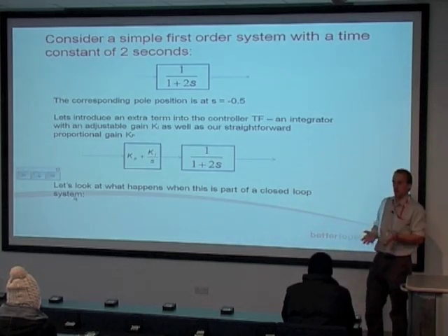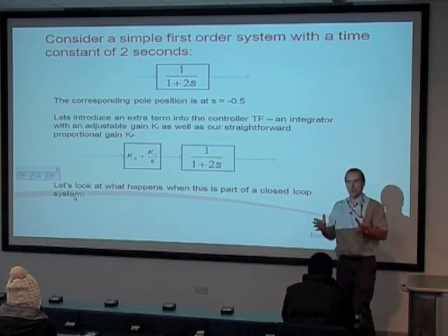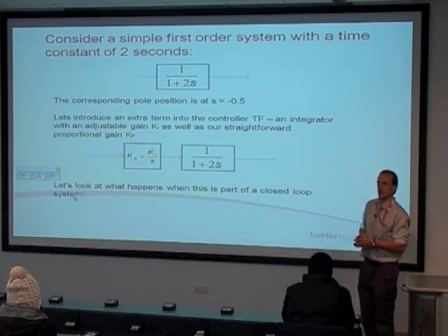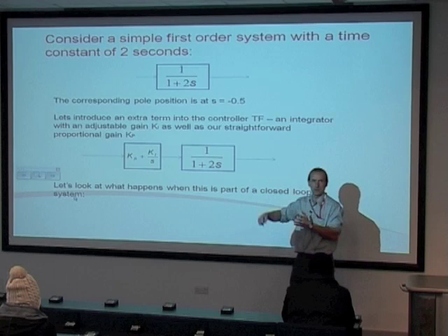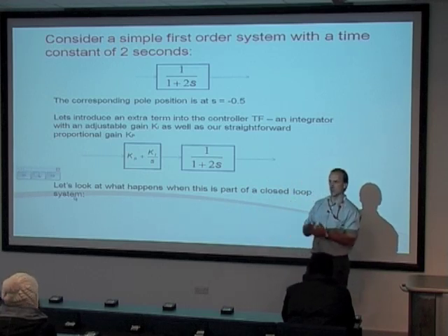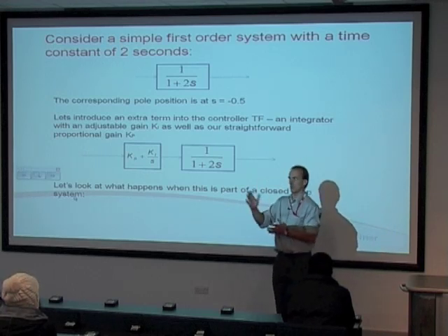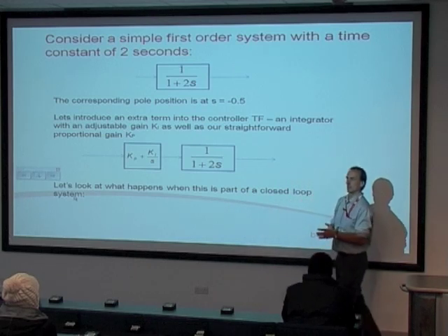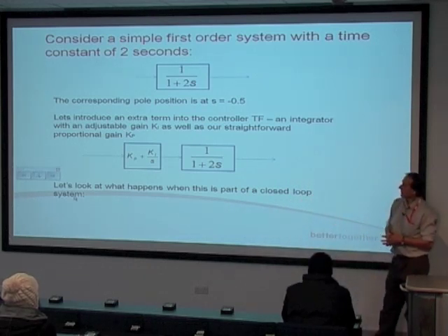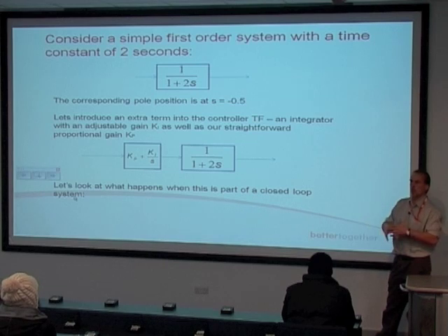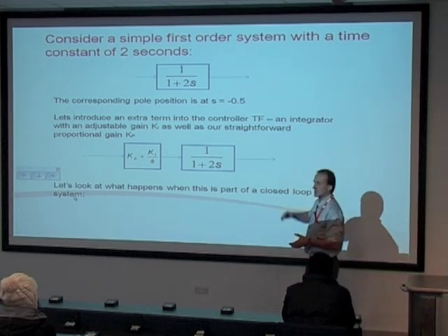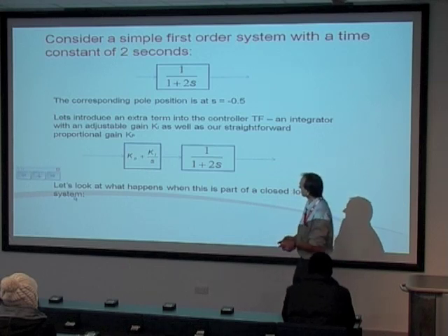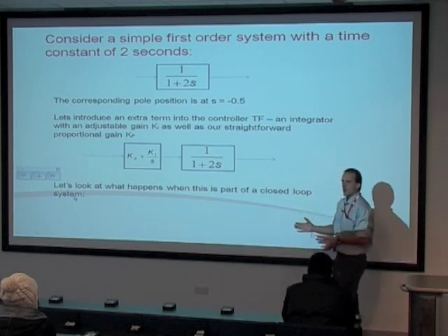And that's a fairly typical proportional only controller. Things that can happen with those, if you get it wrong, if you make K too big, is you can push the system into oscillation, and you end up going down the motorway varying in speed. Too fast, too slow, too fast, too slow. So in that situation, typically we wouldn't simply rely on the proportional control. We'd start to introduce some of these other terms. So that's the preamble.